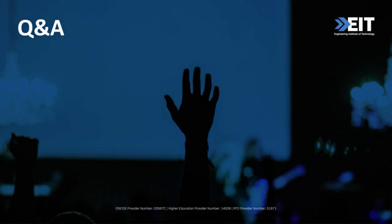So I saw that there was a question from Navid. Yes, no one shouldn't work on a live switchboard. You're correct. The Form 4 is about your continuity of supply. So by having things segregated from one another, such as in a data center, a fault on one is not likely to affect another service. So it's more protection of your equipment.